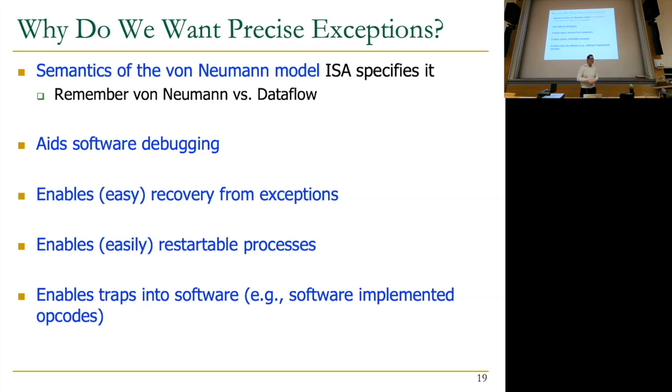And you say that I'm not going to implement multiplication in hardware, but I'm going to have an instruction, and this instruction will be executed by the software. What does that mean? Whenever I see a multiply instruction, I'm going to generate an exception. And this exception is going to take me to an exception handler that's going to do exactly multiply using shift and add, basically, right? And then you're going to return from the exception and get the value.